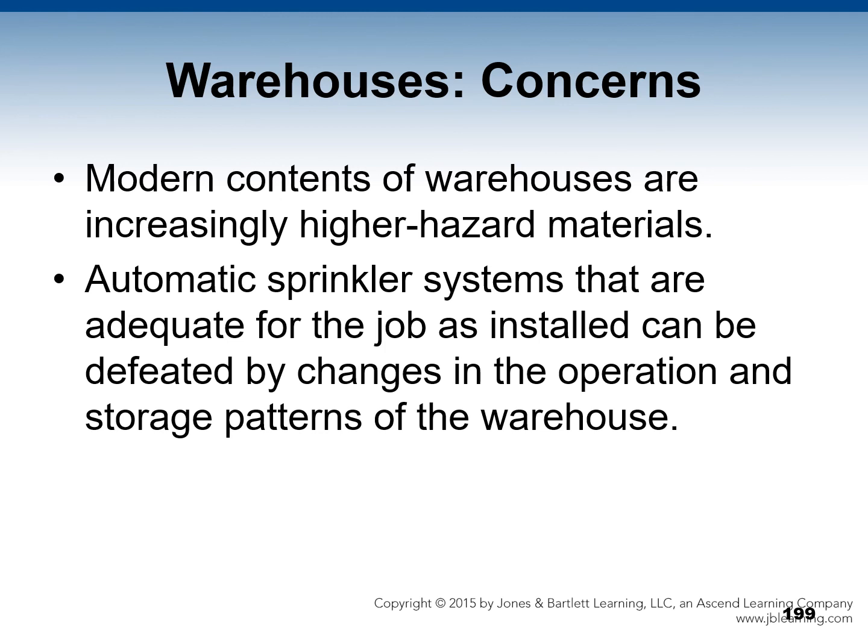Automatic sprinkler systems, as installed, are often inadequate for the potential fire problem. Automatic sprinkler systems that are adequate for the job as installed can be defeated by changes in operation and storage patterns of the warehouse.